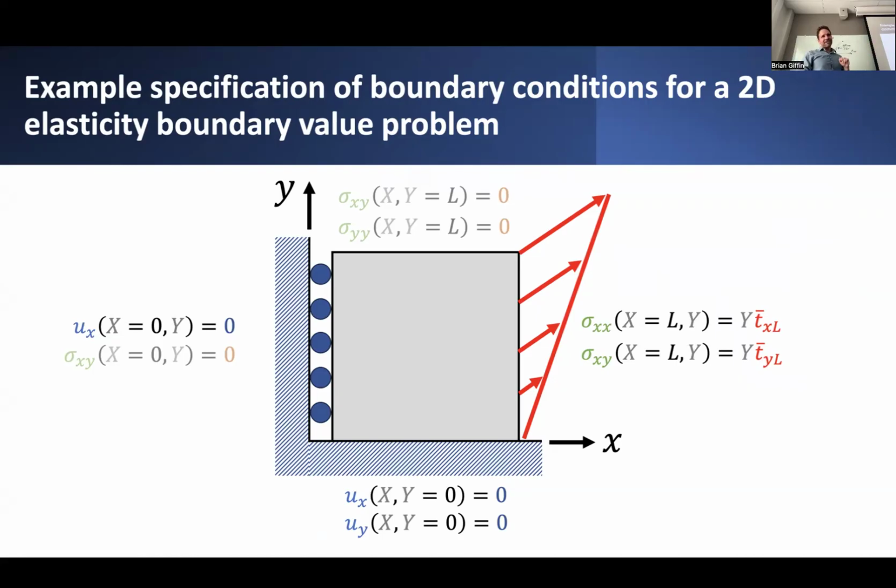On the left surface, let's kind of put some rollers in there, just make it fun, which basically implies that we'll disallow normal displacement. Maybe it allows there to be some kind of normal tensile stress to develop, so it doesn't uplift or anything like that. So it basically prevents any kind of normal displacement, but also, we're not necessarily constraining transverse displacement.